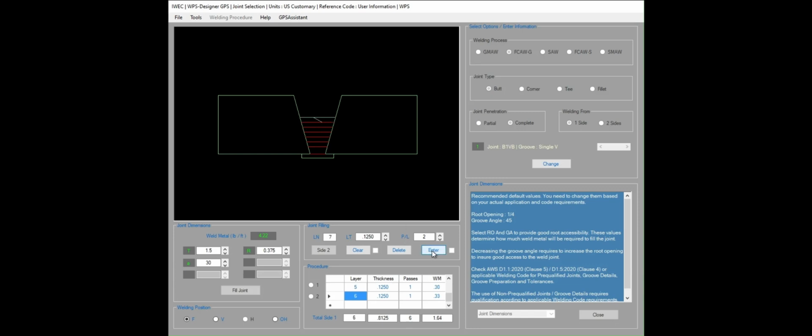The number of passes will affect notch toughness as bead size is related with heat input. As the number of passes increases, the amount of distortion and residual stresses increases. A balance must be established between a few large passes and many small passes.